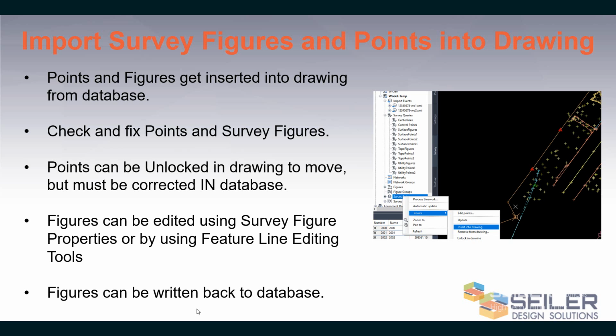Survey figures, on the other hand, can be edited in the drawing, and then, depending on if they're vector or coded ones, it'll automatically update the survey database, or you write them back to the survey database. You can also create survey figures brand new from the drawing and write those to the survey database as well.